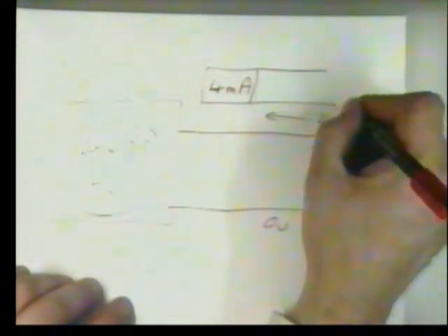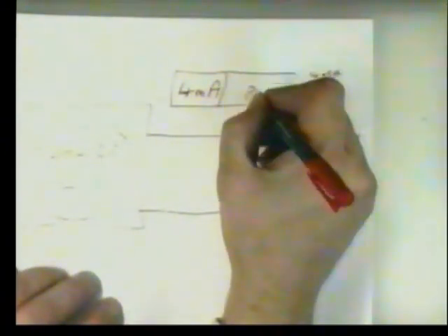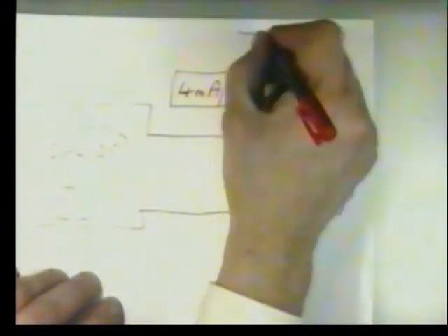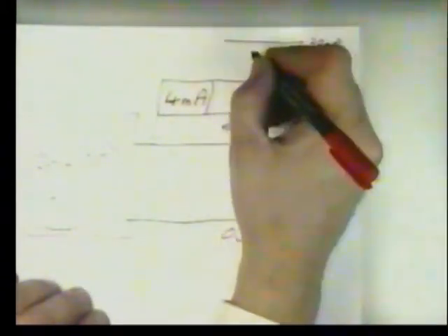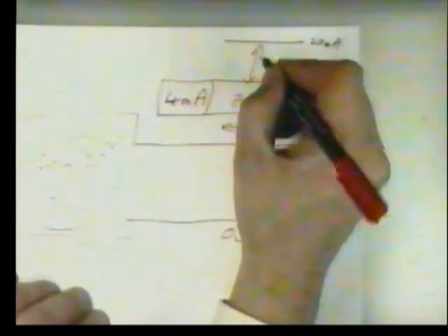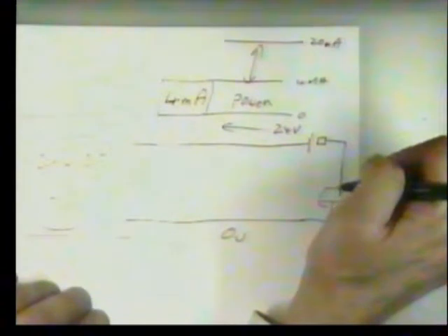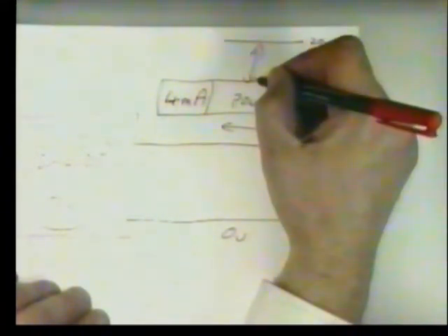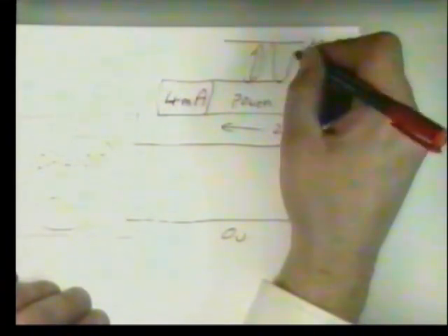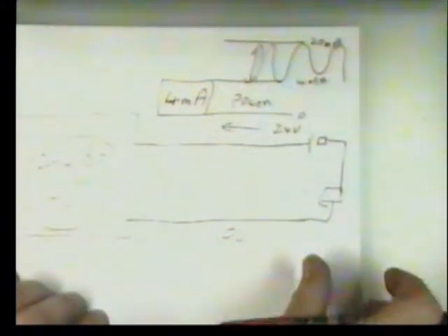The way it modulates the data is that, if we think of 0 to 4 milliamps, that is just the power to drive the unit. But in fact, we're able to draw up to a maximum of 20 milliamps, if we so wish, from the remote battery. And what we do is that in this area here, we modulate the transmitted information in the top of the band.